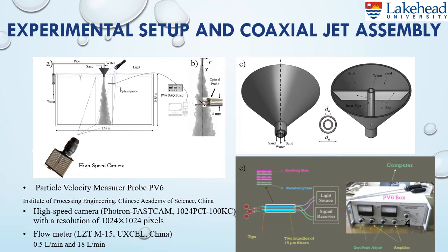The axial and radial distribution of the sand concentration and velocity were measured by an advanced optical fiber probe with two light sensors as shown. Therefore, the cross-correlation technique needs to be performed between two signals to obtain the instantaneous velocities. In addition, to investigate the flow properties such as mixing and periodic motion, higher frame rate snapshots were recorded by using a high-speed camera.